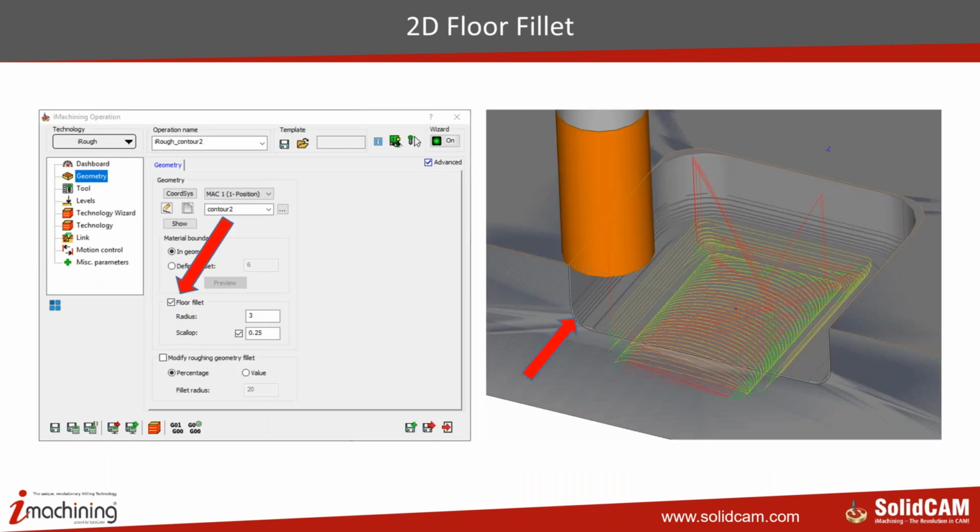Another very important function we have introduced in iMachining 2D is the 2D floor fillet. Suppose you want to use a flat end mill and introduce a fillet at the bottom without modifying the 3D model, where the target model has a sharp corner. This function is now directly available under the geometry function. You can introduce the fillet, define the radius value, and define the scallop you would like for this fillet generation. Using a flat end mill cutter, you can generate the bottom floor inside the iMachining 2D strategy.